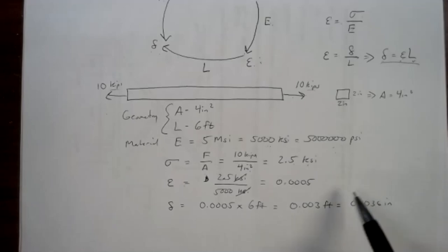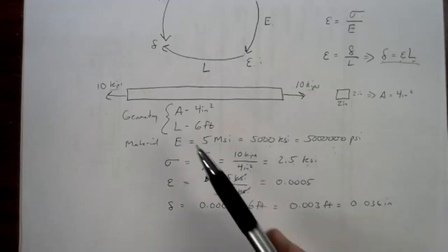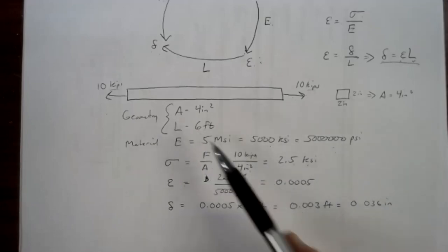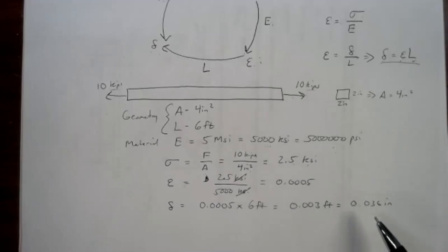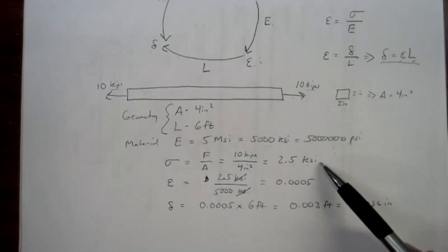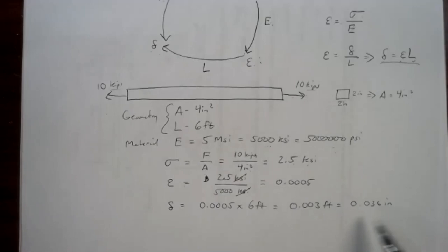You do have another opportunity for a check here. If this ends up being thousandths of an inch, you're probably okay. If it ends up being inches, you might want to worry. If this thing is only a few feet long and it grows by 1, 2, 3 inches, I'd start to be worried that I'm really pushing the limits of the material and this isn't a good model anymore. I've kind of broken things by pushing it too hard.